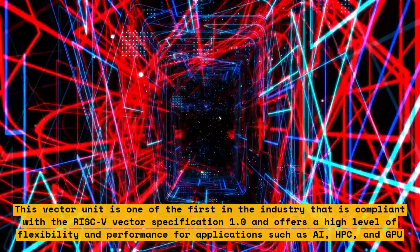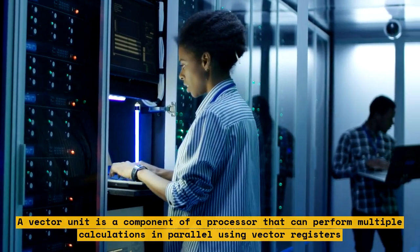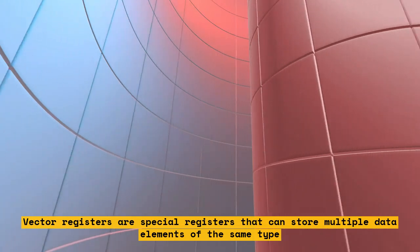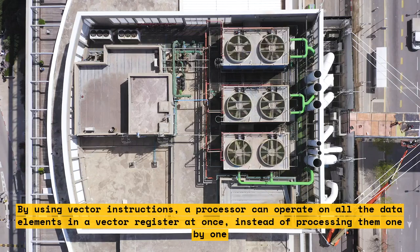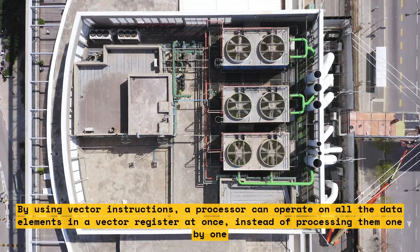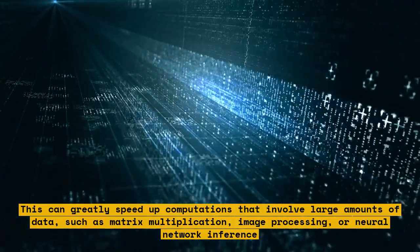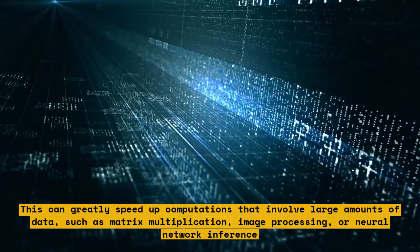A vector unit is a component of a processor that can perform multiple calculations in parallel using vector registers. Vector registers are special registers that can store multiple data elements of the same type. For example, a vector register can store 4 32-bit integers or 2 64-bit floating point numbers. By using vector instructions, a processor can operate on all the data elements in a vector register at once instead of processing them one by one. This can greatly speed up computations that involve large amounts of data, such as matrix multiplication, image processing, or neural